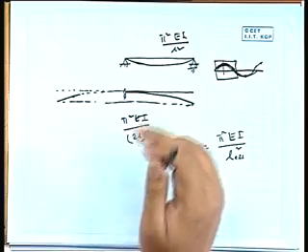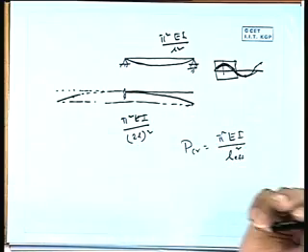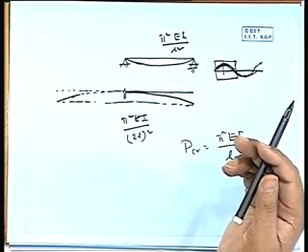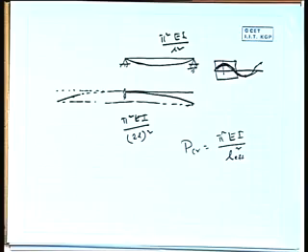Now I am taking a different case now, and without deriving we will find out the critical load from that understanding. So two cases we have derived. One is the fundamental case, both ends hinged. Another is the cantilever case. Next case, say both ends are fixed, right.